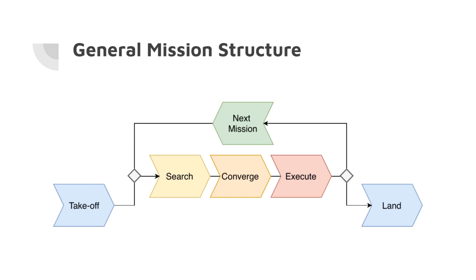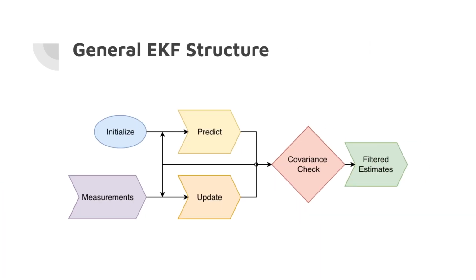A standard EKF is used as an observer in most cases, but here it is used to filter out false detections provided by the vision algorithms. A reliable detection can be defined as one where a series of detections happen within a short period of time. For example, 10 detections in 1 second can be safely considered reliable. On the other hand, detections that happen very rarely cannot be trusted. Hence, the EKF, by the virtue of having covariance as a part of its state, is used here to measure the detection reliability and to supply only trustworthy measurements to the mission node.